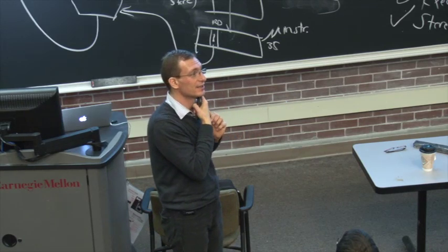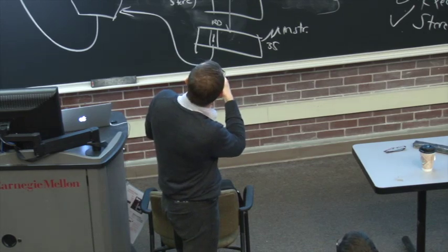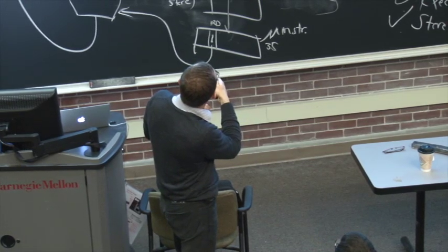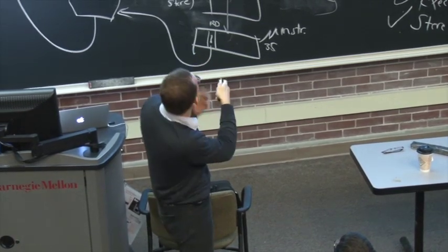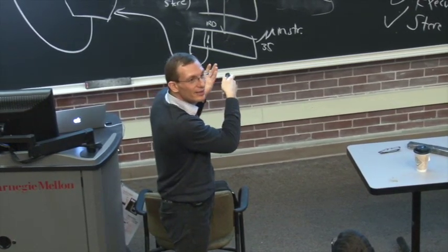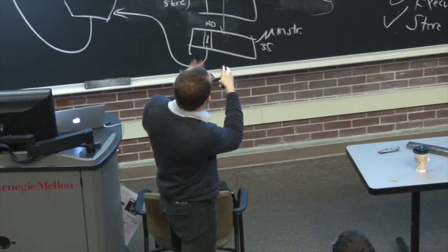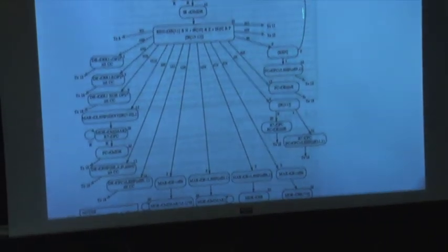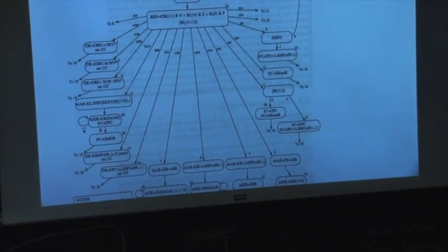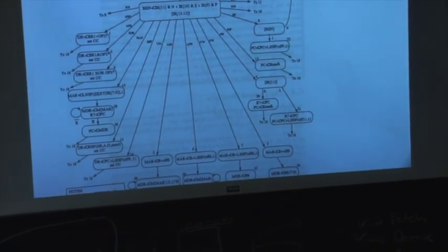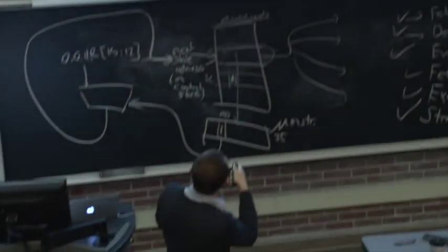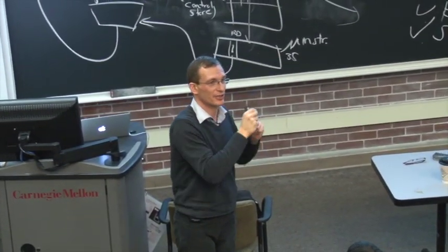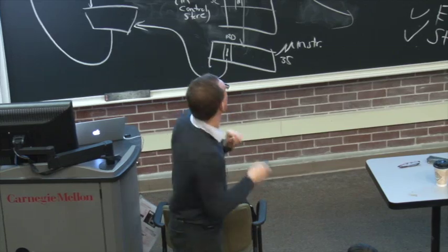That's the semantics. So there's some logic that needs to compute whether the condition of the branch is met. Right? And that's computed in this state. Well, why is it computed in this state? Because maybe you don't want this logic to determine your next state's control signals later. Again, you're trying to overlap the next state computation earlier. You don't want to have that be on your critical path.